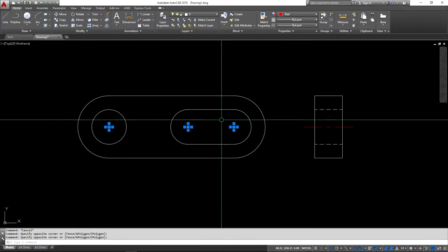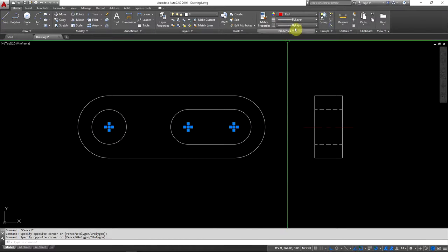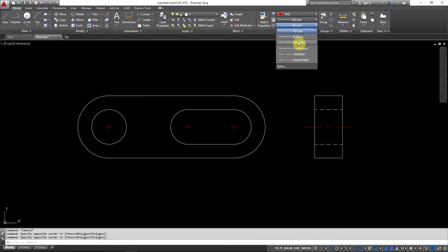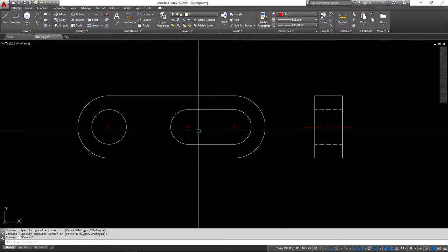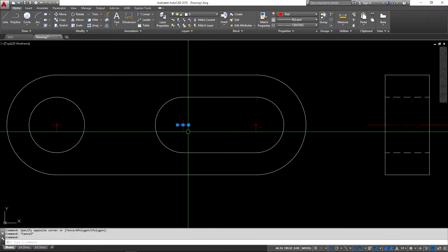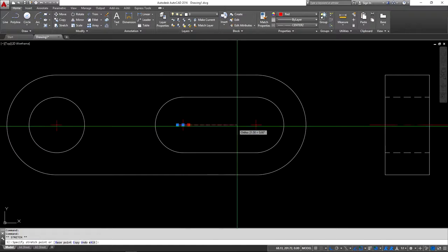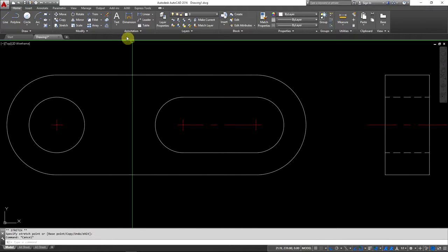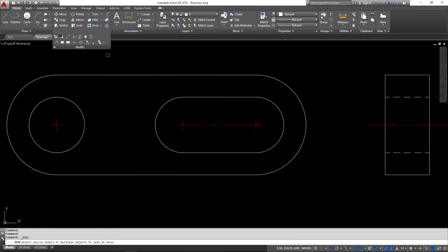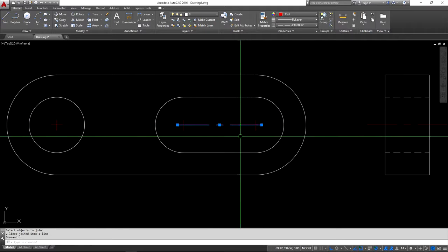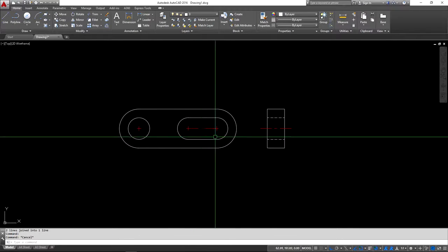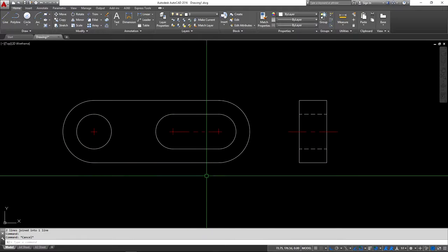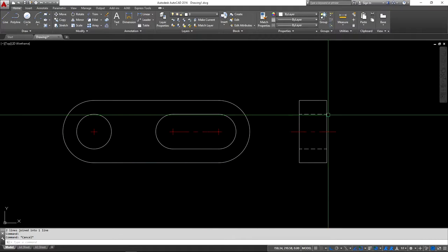Now even though they're too small to be able to see the center line, I'll still change the line type to center just in case I want to do something like grabbing this endpoint here and stretching that across to there. Then under the modify tool, using join, I can join these two together, so that's now one object, and now you can see the center lines there. Okay, so that's pretty much one way of drawing this.